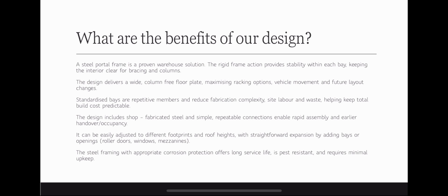Our steel portal frame design offers a wide, column-free interior for flexible racking and vehicle movement. Standardized repeatable bays reduce fabrication time, site labor, and waste, keeping costs predictable. Short fabricated steel and simple connections allow rapid assembly and early handover. The frame can be easily expanded or modified, and with corrosion protection, it ensures long service life and minimal maintenance.